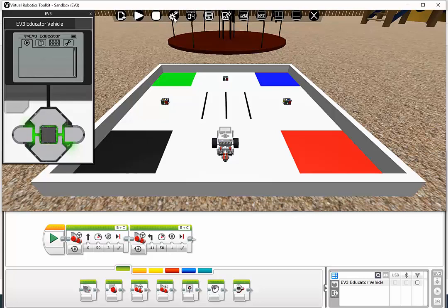Now the next button is the attachment dialog. Each project comes with its own pre-built robot, but that is not what we want. We want to add attachments to it. We want to customize it. Sometimes we actually want to create it from scratch. All these capabilities I just talked about are present in Virtual Robotics Toolkit. However, in this simple mode, which has a simple toolbar with only a few options, you only have the capability to customize your robot, not build it.